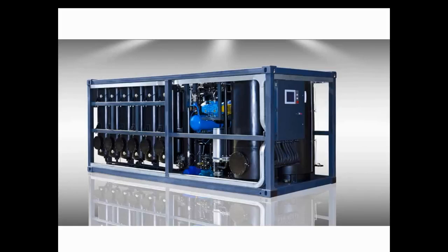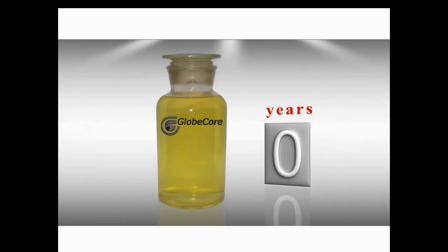When due to the aging process, oil in a transformer reaches a stage, which can be a period of 10, 15, up to 20 operational years, where oil purification, degassing, is no longer effective, oil must be either changed, what they mostly do today, or regenerated, what would be a perfect alternative. Regeneration is the complete treatment of oil to like new condition.